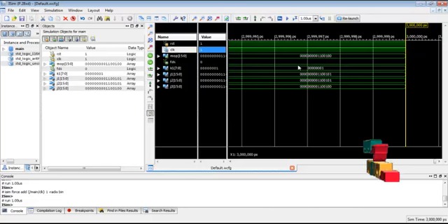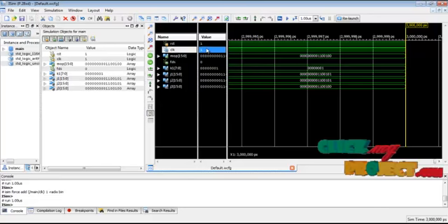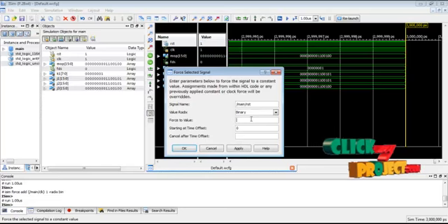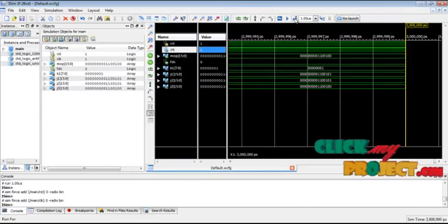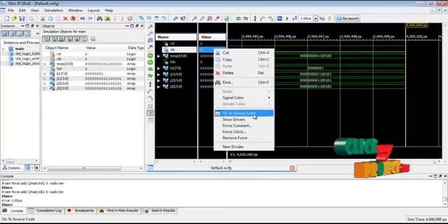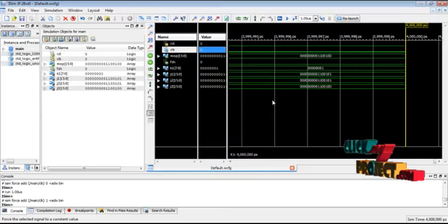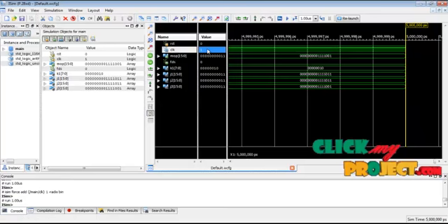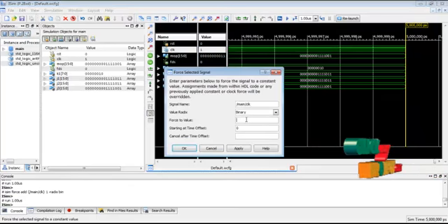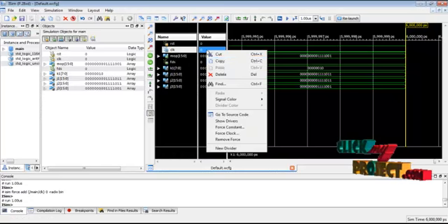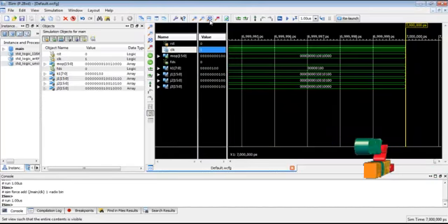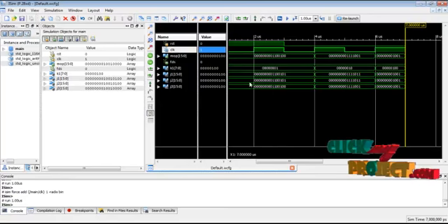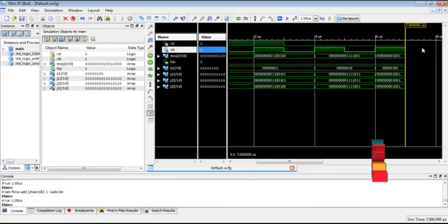With the initial reset function, we apply the initial bit allocations. Then we remove the reset function and apply the clocking sequence one by one, generating the test input patterns and creating the output pattern results. These are the overall multiplication results for every clocking sequence.